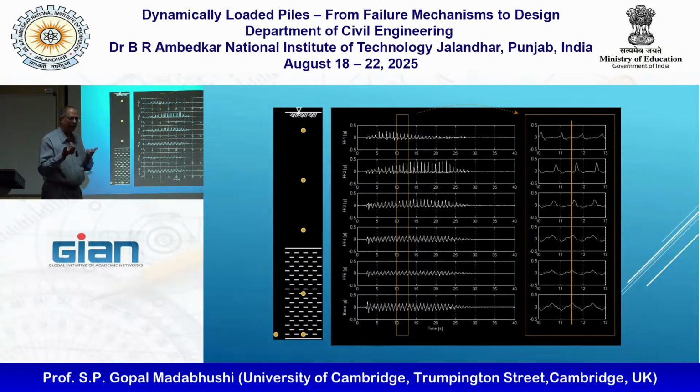So there's a lot of information you get, which means if I know the delay, I can work out shear wave velocity. If I can work out shear wave velocity, I can work out what the reduced shear modulus is. All that information is coming straight from the accelerometers.